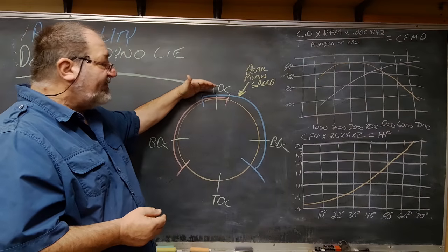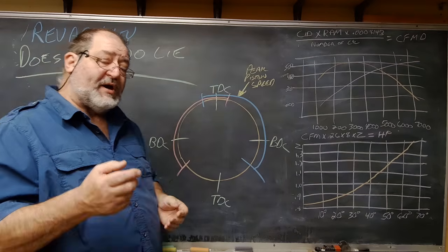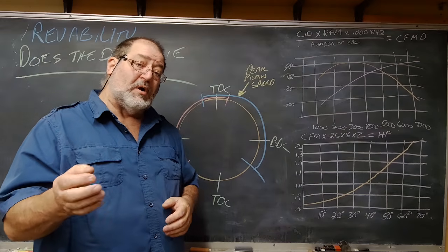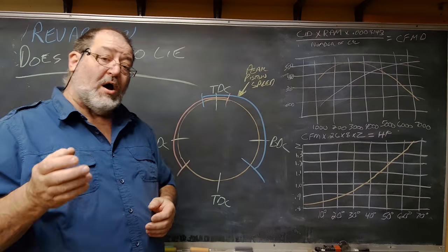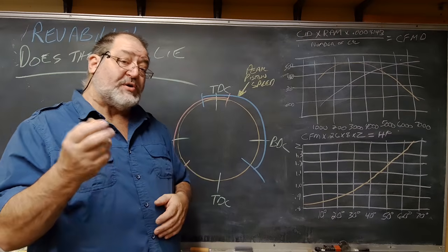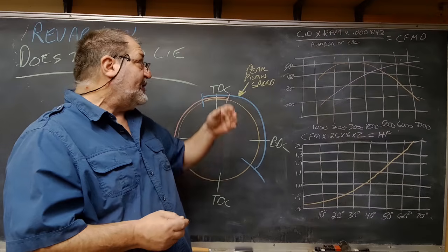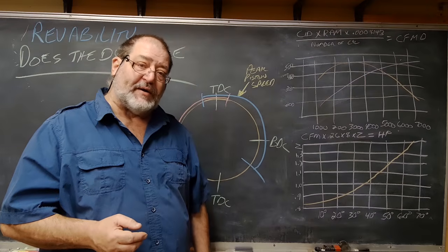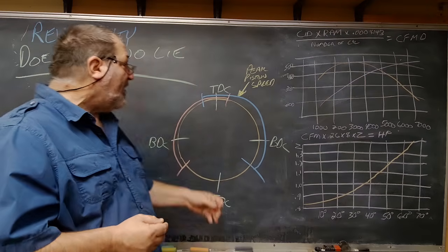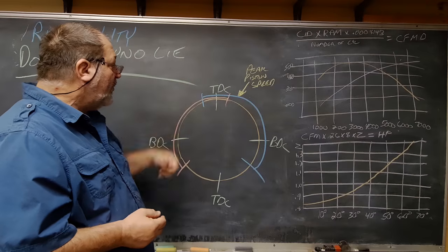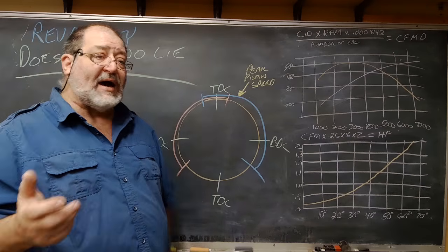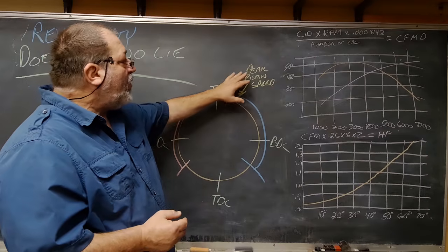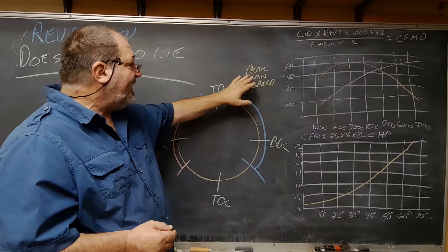because you've got piston to valve clearance, especially on a performance motor where you're trying to get compression out of it, and you have a certain head you have to run. Well, you are fighting to have room for the valve to open. A lot of times, it's not what I want to be open here.